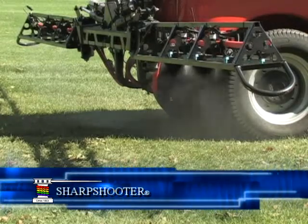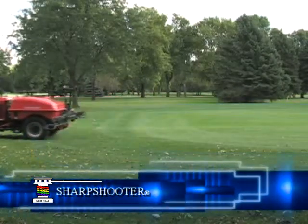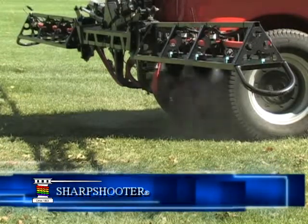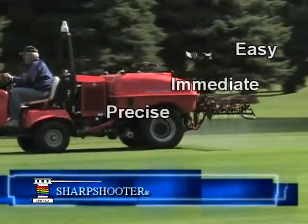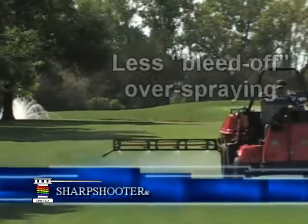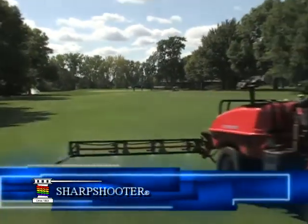Sharpshooter controls the on and off spraying function right at the tip, and shutoff is instantaneous. The liquid and pressure are retained in the boom at the tips, so when the boom is turned on, there's instantaneous flow at the proper pressure. That makes starting and ending an application pass easy, immediate, and precise. The quality opportunity amounts to less bleed-off overspraying of chemical when the boom is turned off. Likewise, there's less pressure-up underspraying that results in several feet of under-application when turning the boom on again.